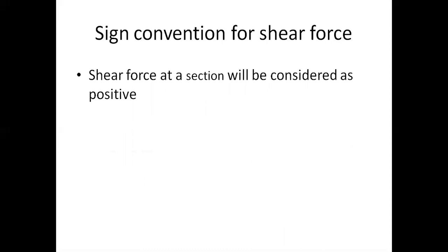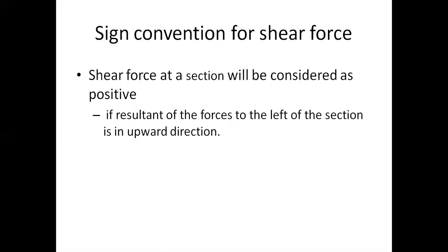Shear force at a section will be considered as positive. Shear force at a particular section will be considered positive if the resultant of the forces to the left of the section is in the upward direction. Left side and upward direction, then it is positive.